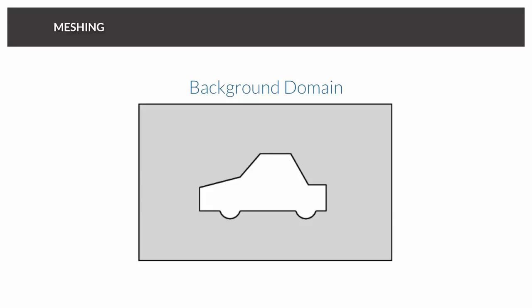Usually it's a bottom-up approach, which means you need to mesh first edges, faces, surfaces, volumes, and so on. This time, you actually start with the background mesh, and you just define local refinements. And let's go through the process.